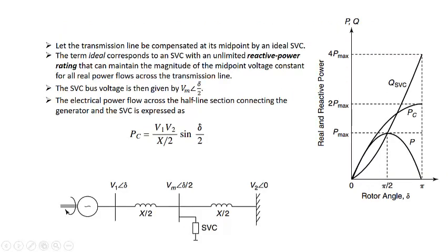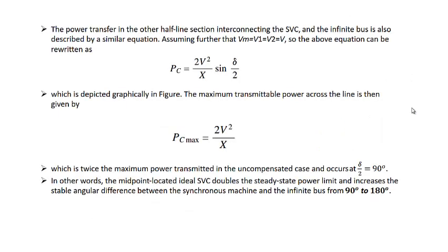That means earlier you can see for an uncompensated system, the system was stable for the slow changes in the power. It was stable from 0 to 90 degrees, and it was unstable beyond that, because when mechanical power increases, electrical power is not there to compensate that power. It will then decrease for increasing rotor angle. But when compensation is done, you can see the power angle will always be increasing. The instability problem will be eliminated for this case. That is what is meant.